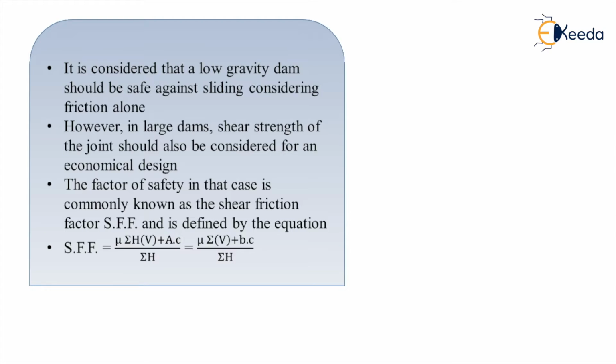But if the gravity dam is large or high, then because of this large and longer length, we have to provide various joints also. Because of this joint, the shear strength will be developed, and we have to consider this. The factor of safety in that case is commonly known as the shear friction factor.